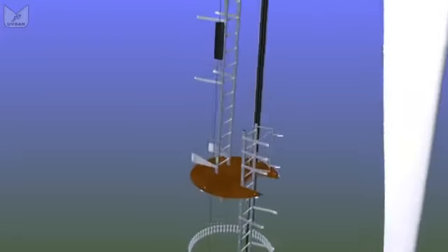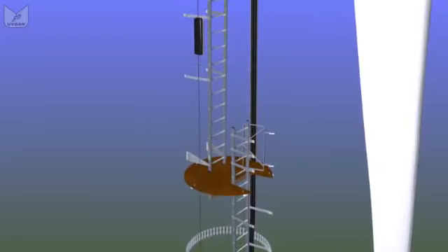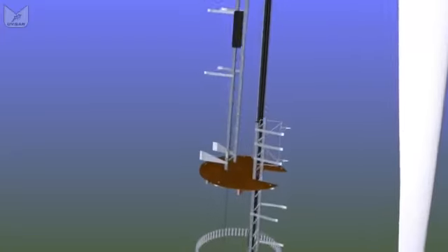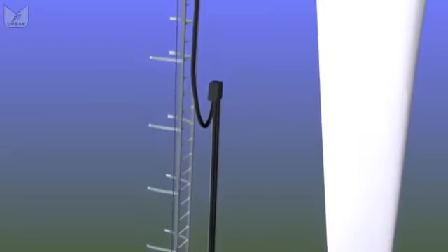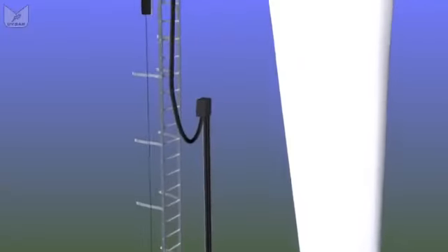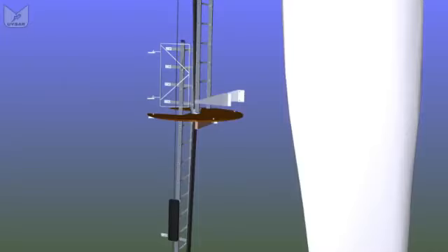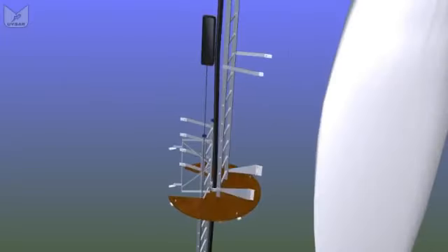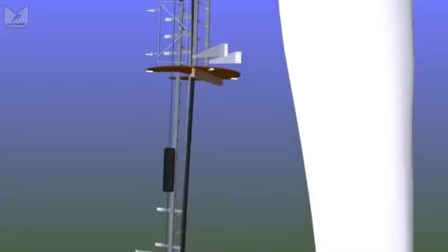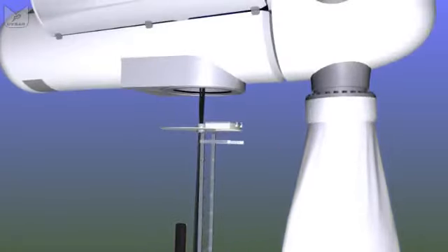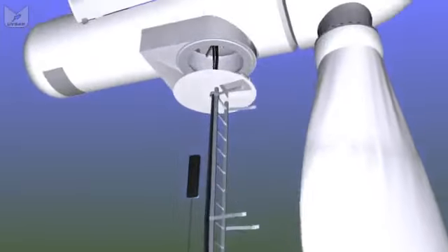But eventually the main cables stop being attached to the wall and they hang freely in the centre of the tower, so they can twist as the nacelle rotates to face the wind. If they twist too many times, the nacelle will spin itself around to remove the twists. But as we move up, now the cable goes through a hole in the centre of each platform, and at the top of the tower we have a steel platform with a sealed trapdoor, which we call the yaw platform.